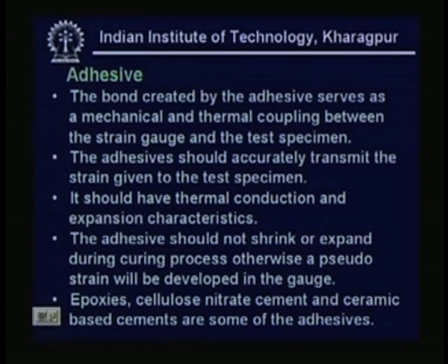It should have thermal conductance and expansion characteristics the same as the metal itself or test specimen. Thus, adhesives should not shrink or expand during the curing process, otherwise pseudo strain will be developed in the gauge. This is also very important, because the curing process means you have to leave it for at least 24 hours to dry up. Once, suppose in my pipe, I put a strain gauge here, so I put an adhesive,